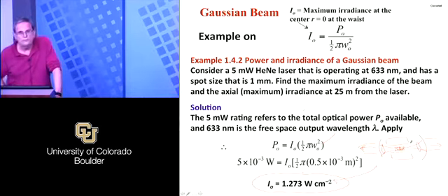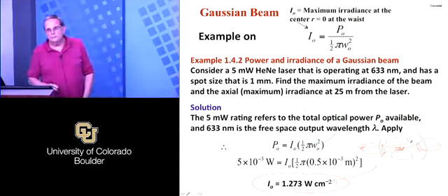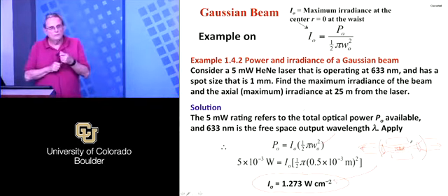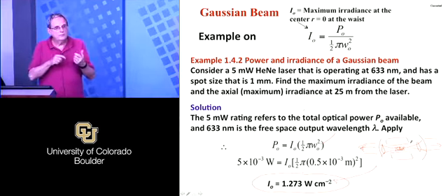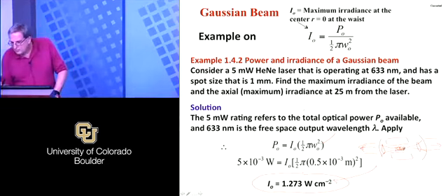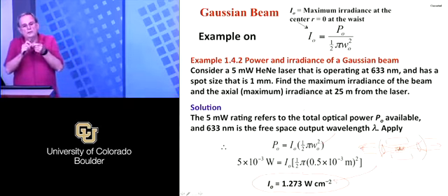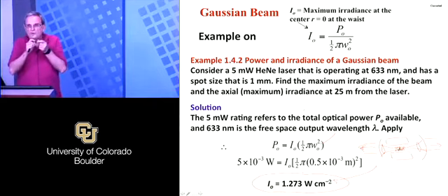The green ones, though, you have to double the beam. There, essentially, you use a gallium arsenide laser that's at 830, and you actually double the beam wave, or actually use a neodymium YAG crystal inside of those, and then you have a beam doubler. It's amazing how cheaply they can make those. If you pull one apart, everything's integrated into essentially a single crystal with the optics integrated into the same piece.